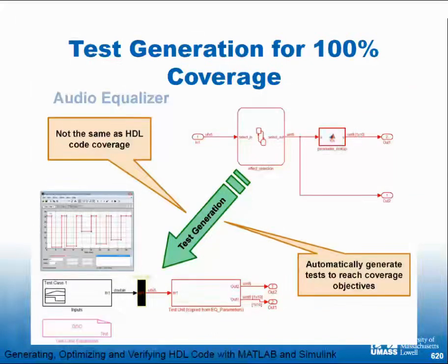If this was a processor design with a bunch of peripherals, I would maybe use the autocoder to write my C code that's going to run on that processor, but I wouldn't use this to generate a processor. A communication system depends. Most likely I would, at least for the communication peripheral, because again, you're doing stream processing.